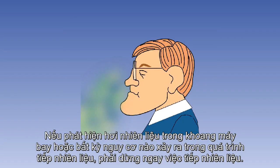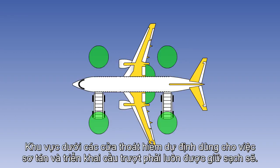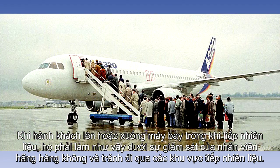If the presence of fuel vapor is detected inside the aircraft, or any other hazard arises during refueling, fueling must be stopped immediately. The ground area beneath the exits, intended for emergency evacuation and slide deployment areas, must be kept clear. When passengers are embarking or disembarking during fueling operations, they should do so under the supervision of an airline official, and their route should avoid the fueling zones.